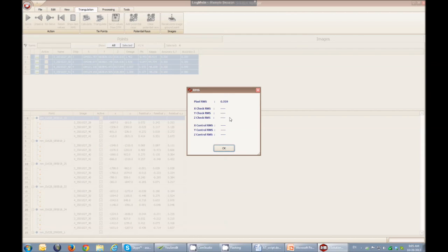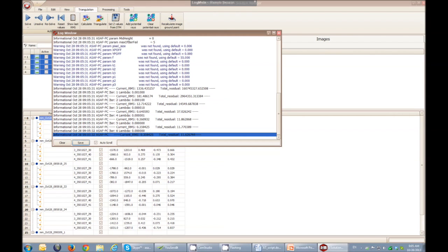The bundle adjustment residual mean square value will be shown at the end of the process to show the geometric integrity of the model. High RMS values indicate poor geometric integrity. A good model usually has less than 1 pixel value. The bundle adjustment process can be repeated until an optimal model is achieved.